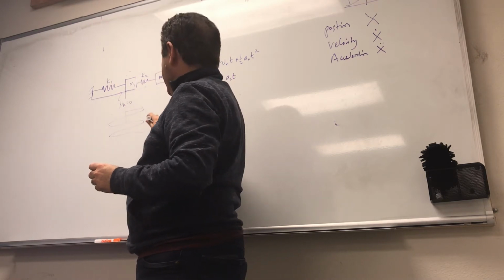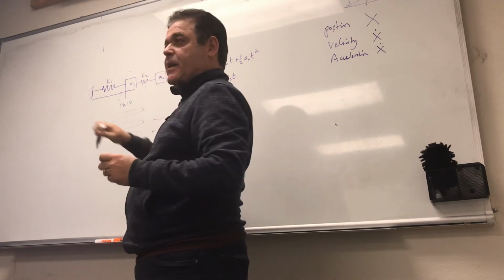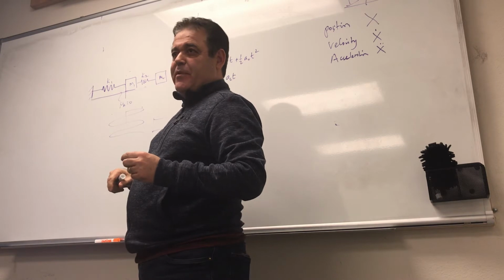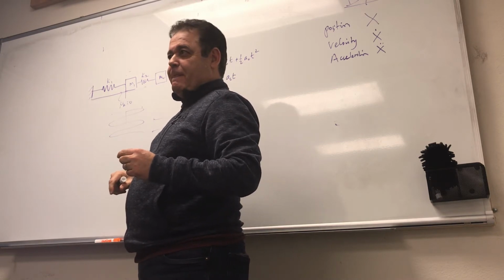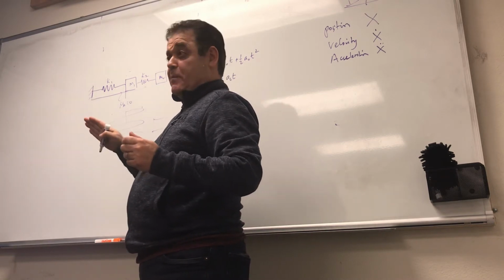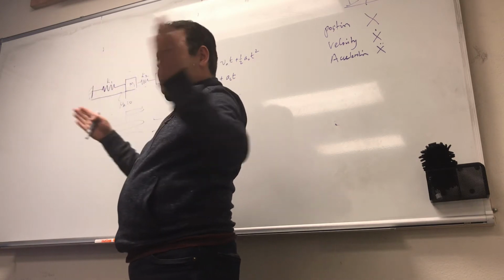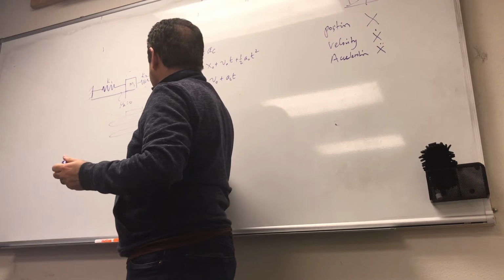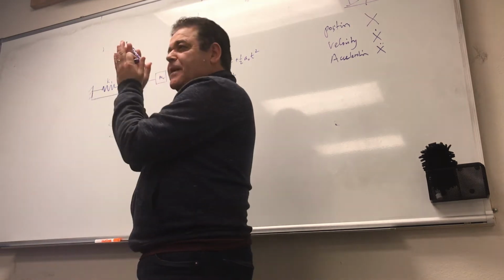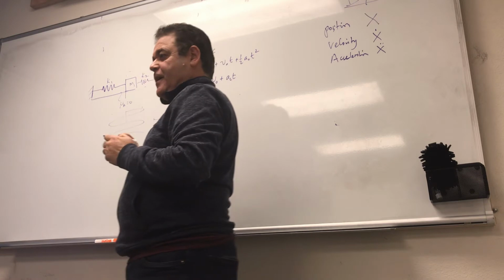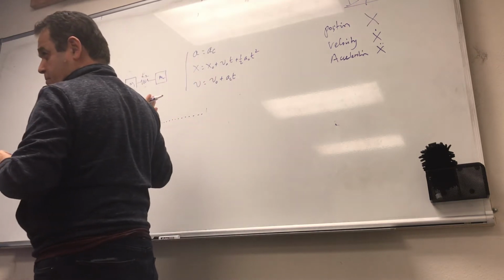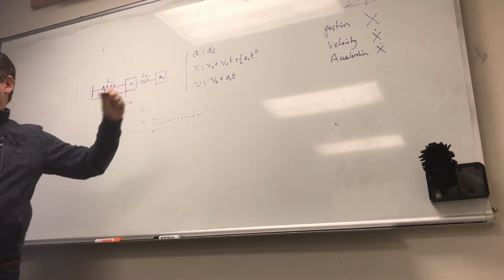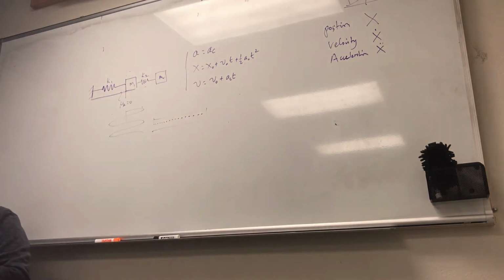Now, when you get to, let's say, a cantilever beam or something like this that you pull down and let go, how many degrees of freedom do you think there are? An infinite number, because it's a continuous system, right? So you can model this as a lot of little masses, one after the other, and we're not going to get into solving those because those are continuous systems as opposed to these guys, which are called discrete systems.